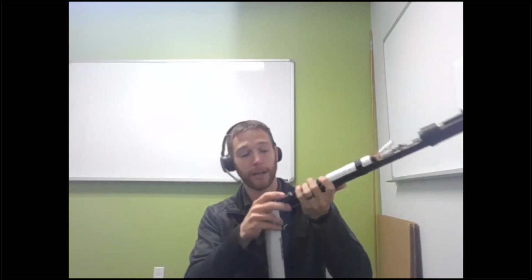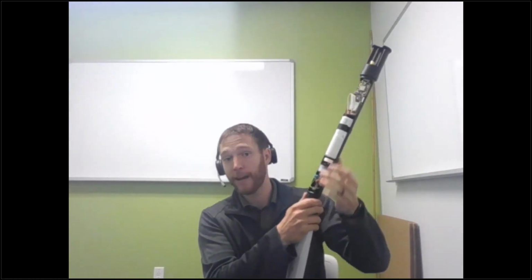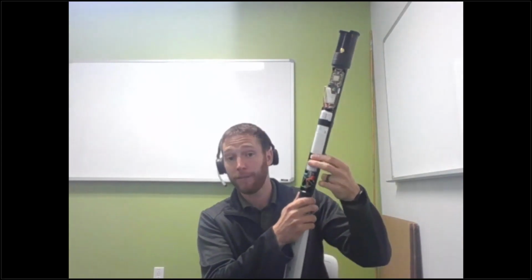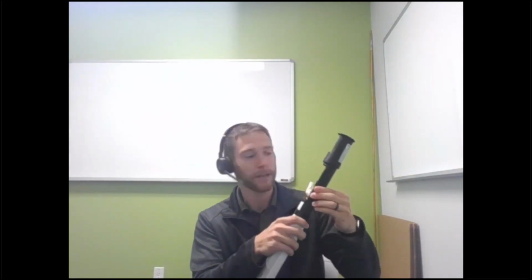There are a couple of different desiccants in there. I should have mentioned the pressure transducer is a vented pressure transducer, so it will compensate for changes in atmospheric pressure. That really helps to get a high quality, accurate water level measurement from your device. In order to vent that out, you need to make sure there's no condensation in the line. We do have desiccant in the device that is pretty easy to swap out if it does get saturated. And the logger will monitor humidity within the logger itself to help you understand when you may need to do maintenance on your device.